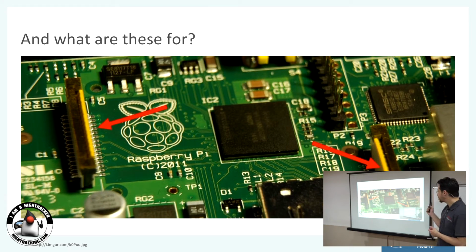Okay, so this display port, I think it's this one here. It's used to hook up to an LCD screen. Unlike the HDMI, which is used for displays or TVs or large electronics, this one powers the display, and it also has touch support, and it doesn't require conversion. Normally, when you have an HDMI screen, it has an electronics board which takes the HDMI signal and converts that into an LCD signal.